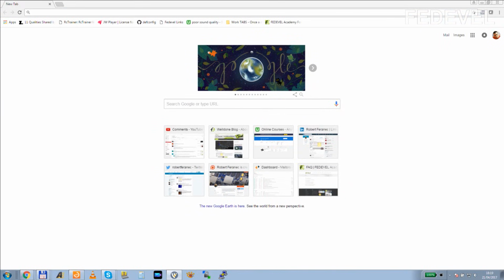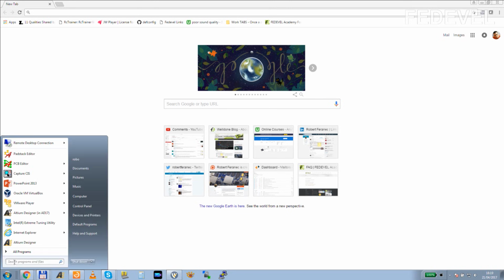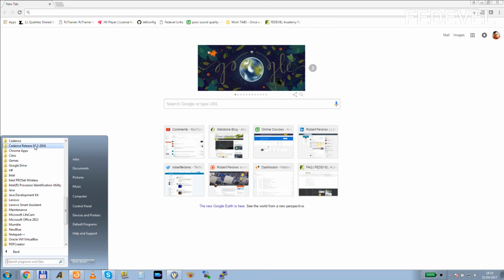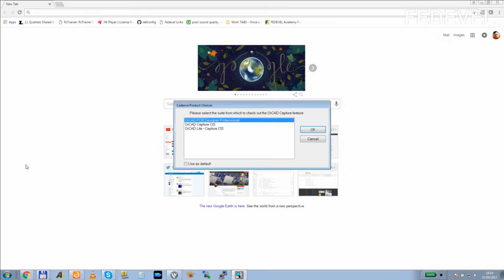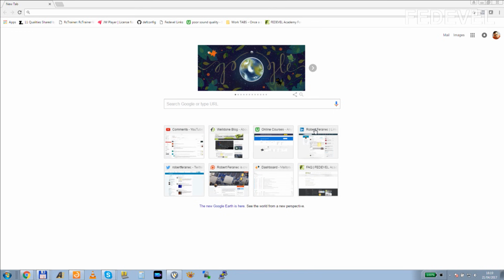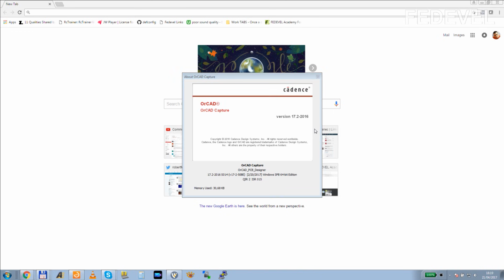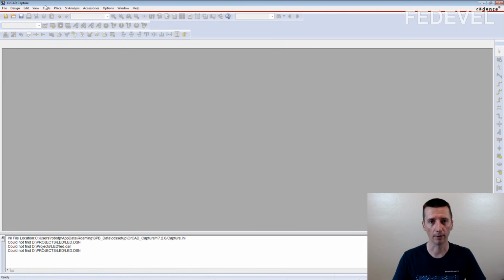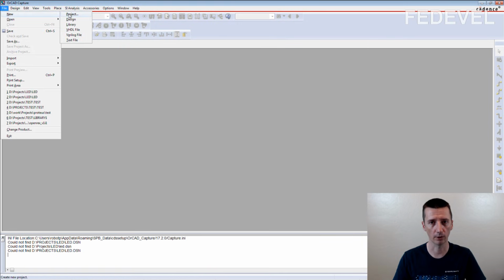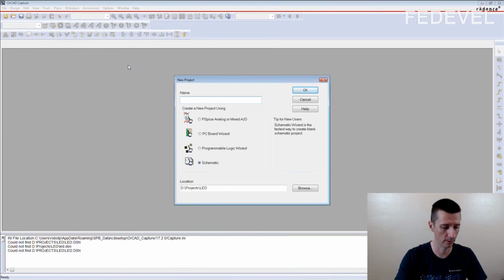Okay, let's do it. First, I'm going to open the OrCad. Click on Start, All Programs, Cadence Release, Allegro Products, Capture CIS. And I will select this OrCad PCB Designer Professional. Click on File, New, Project, name the project, select Schematic, and choose the location where your project is. Okay.